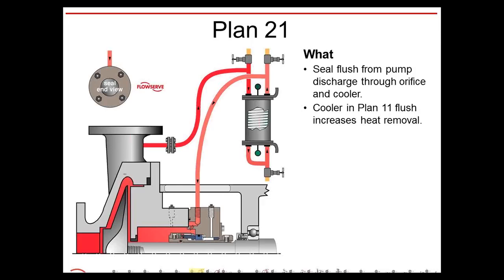cooling capacities. Now, this was once done initially because they wanted to suppress vapor margin by increasing the pressure in the box. Well, if you understand a little something about boiling points, if you cool the fluid in the stuffing box, by cooling it, you simply suppress the vapor margin. So wouldn't it be more advantageous just to cool a small area and get that nice and cool so that it can't flash than to continuously cool hot fluid?